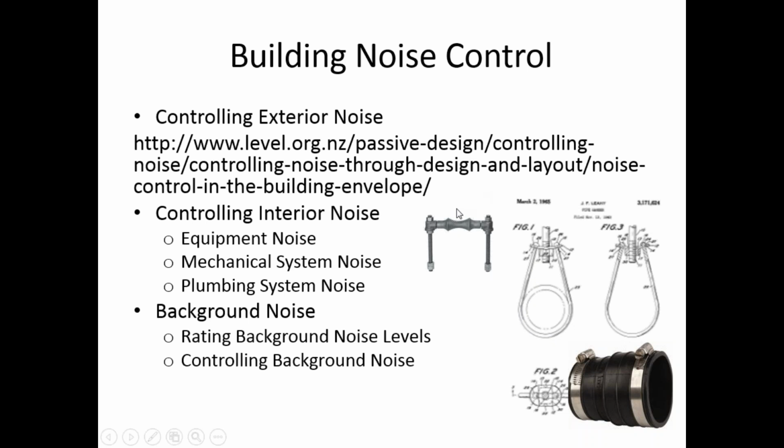So not all of those resilient pipe hangers are created equally. The less metal and the more rubber that we can implement will help us with the shake and the sound problems. And then in the lower right, I have a flexible connection. Some of them are more rigid and involve more metal, and less flexibility can cause increased reverberation and noise problems. So using these rubber fittings that also have a little bit of bend to them will help.